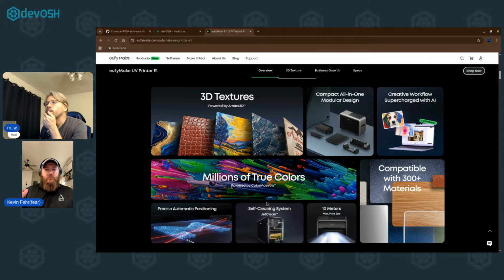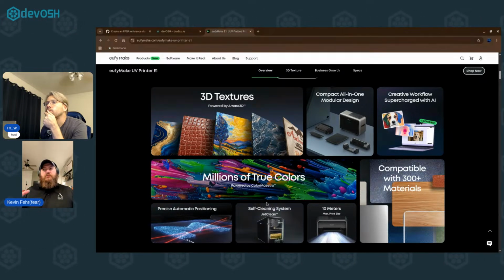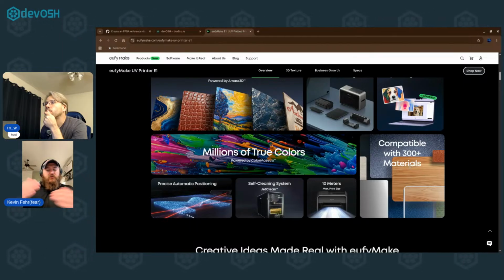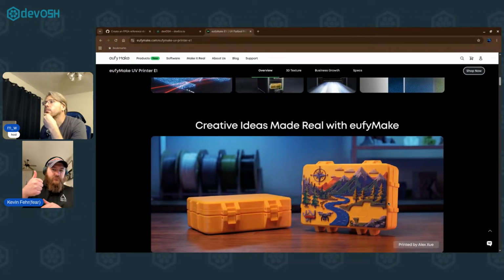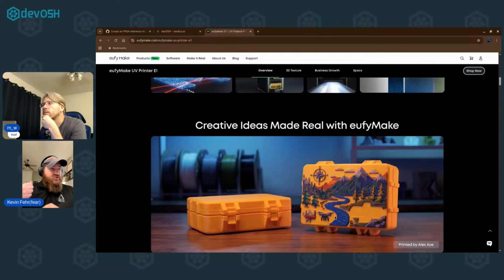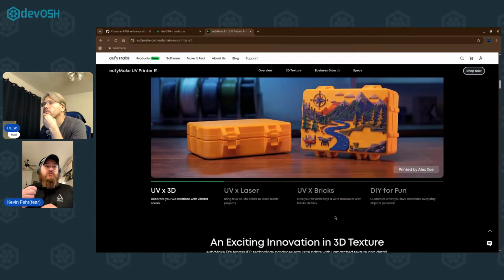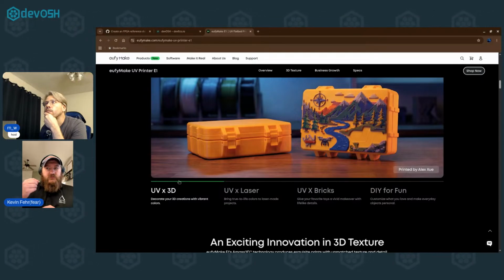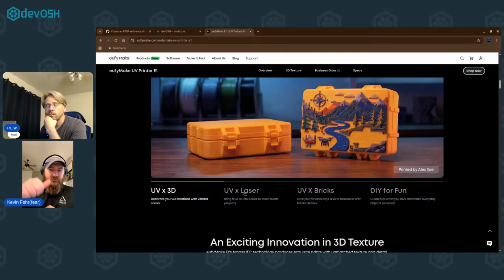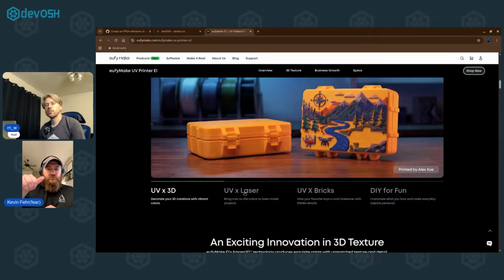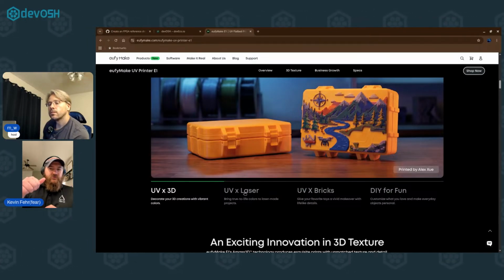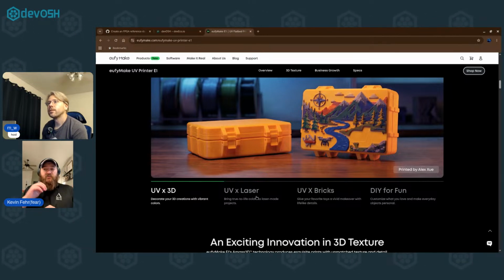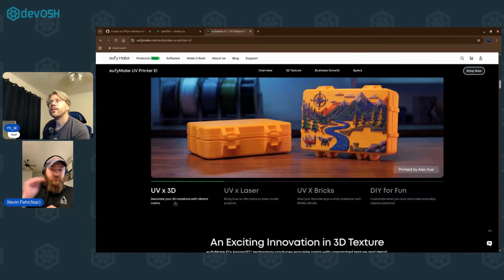It's one cohesive component, because UV printing is anisotropic. So it's one solid thing, and if you make it a little bit thicker, durability goes up significantly. Another thing was prepping your printing surface a little bit better. IPA will do it, but some acetone and more aggressive chemicals to clean the surface will help improve the surface energy of the plastic, or in my case, PLA and PETG, that makes it easier to print the UV on.